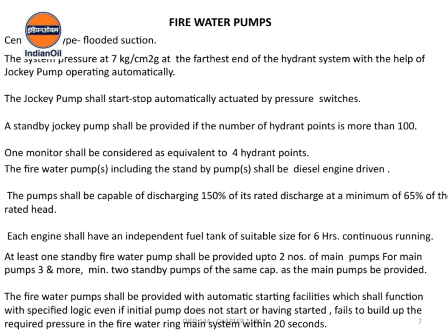The pumps are designed to discharge at 150% of their rated capacity, but they must do so at a minimum of 65% of their rated head, ensuring they can deliver sufficient water pressure when needed. Each pump engine should have its own independent fuel tank, large enough to support 6 hours of continuous operation. This setup guarantees operational readiness during emergencies.